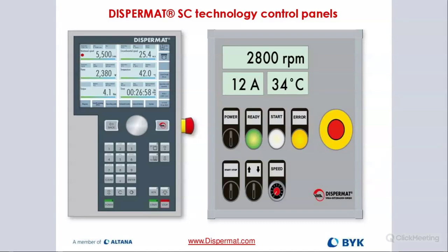is extremely precise, and customers use it to create their own viscosity tables, and they can be done in the lab as well as pilot and production. So that can be really helpful, especially if viscosity is really, really critical for your process. On the top right, we show you the actual tip speed, the peripheral speed. Remember, we said when we are dispersing, we want that value to be between 18 to 25. And when we are milling, we run that with slower speed, 10 to 16 meters per second.